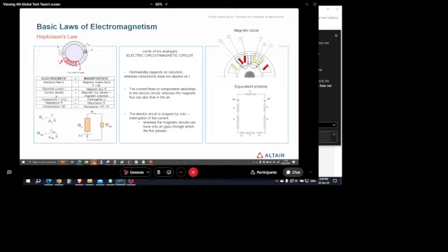The current density, by analogy, we are going to talk about the magnetic flux density. The conductivity is equivalent to the permeability in magnetic circuit. The resistance is equivalent to the reluctance R, and the conductance is equivalent to the permeance, the inverse of the reluctance.